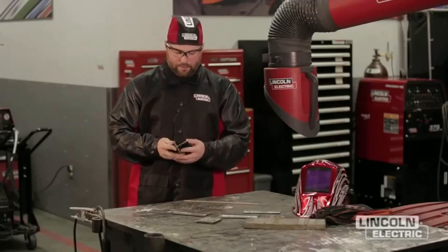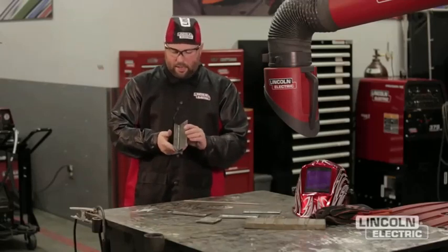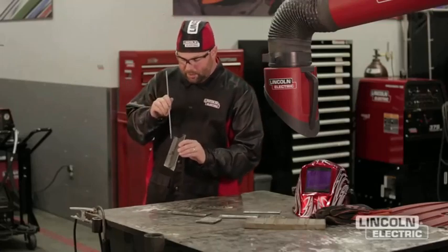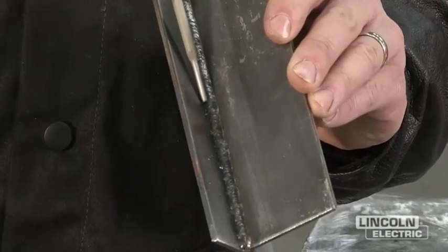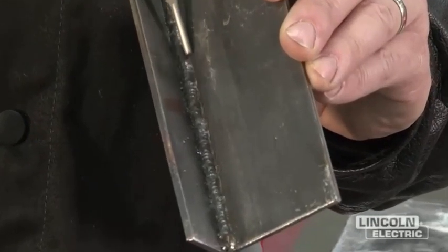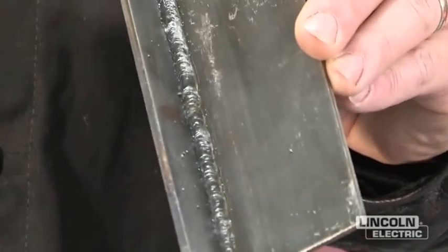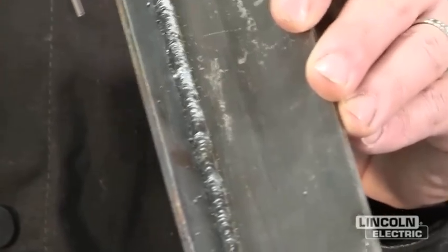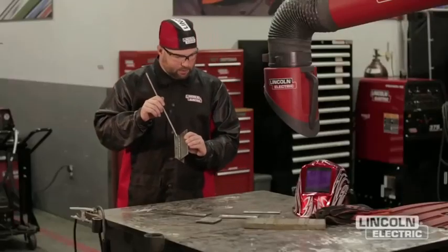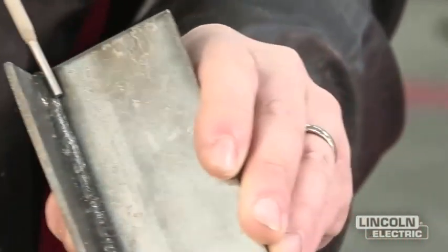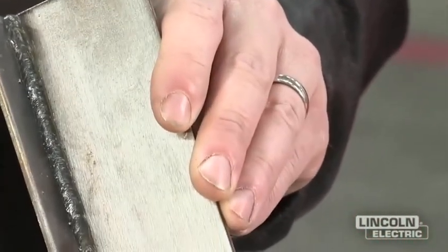So when we look at visual inspection, we're going to take a particular joint, and we'll use this T-joint here to start with, and there's a couple different parts of the weld that we should be familiar with. On this particular weld, we've got a toe of our weld here and a toe of our weld here. The part across the middle is what we refer to as the face of the weld. We want that area from here to here to be relatively flat.